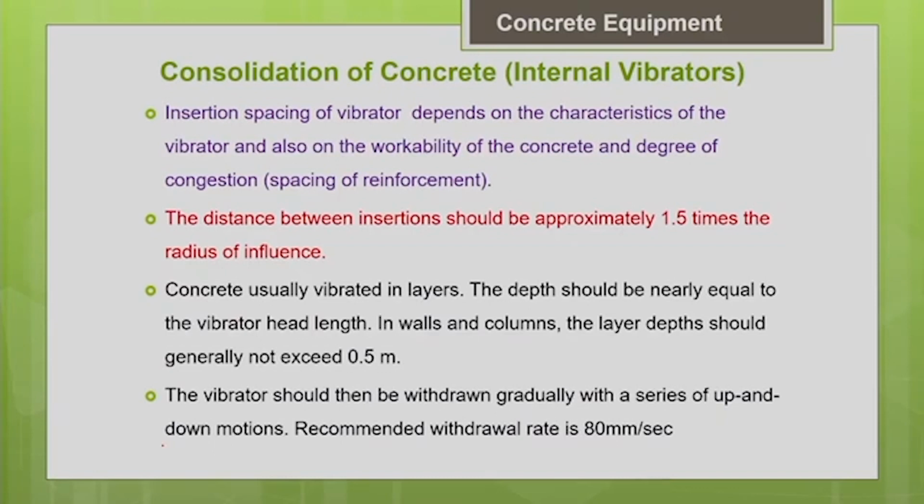But if the concrete has a higher consistency, in that case I can go with lower amplitude and higher frequency. So according to the consistency, you need to vary the amplitude and the frequency, but that is mostly possible only in factories. Very commonly at your job site, you can see that they change the spacing of the vibrator just by looking at the consistency of the mix.